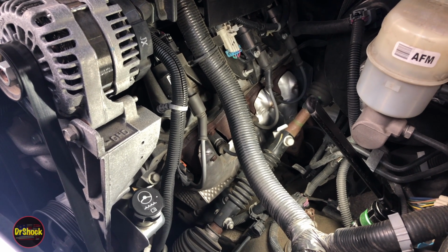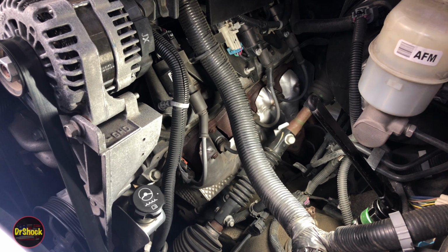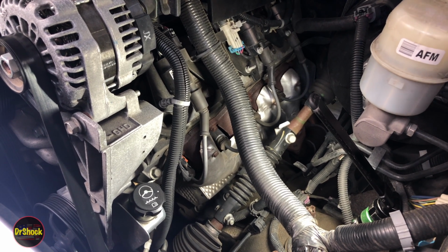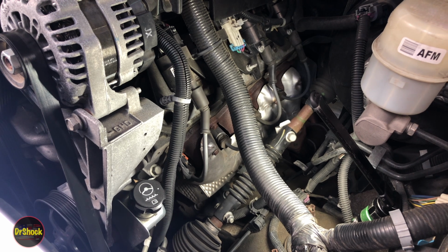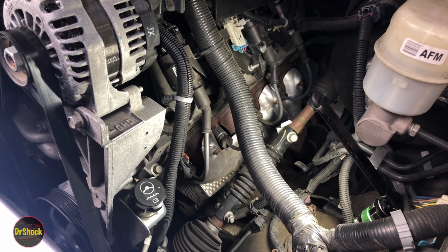We're going to have to go through and do resistance checks on all of the ignition wires, just unrelated to this, but that's another problem. So we want to make sure that everything's to spec, and we're going to have to check all these plugs. So I'm going to go through this, and I'll let you know what we find.